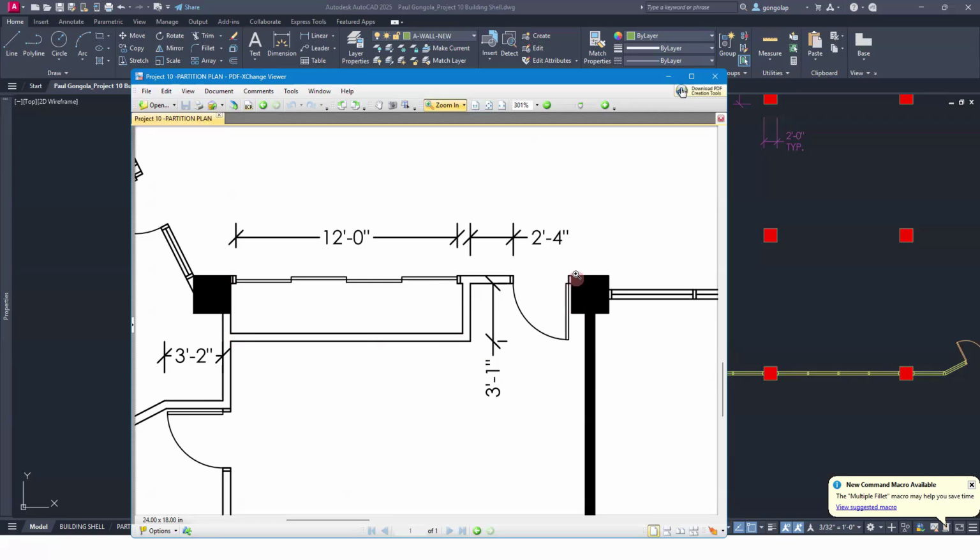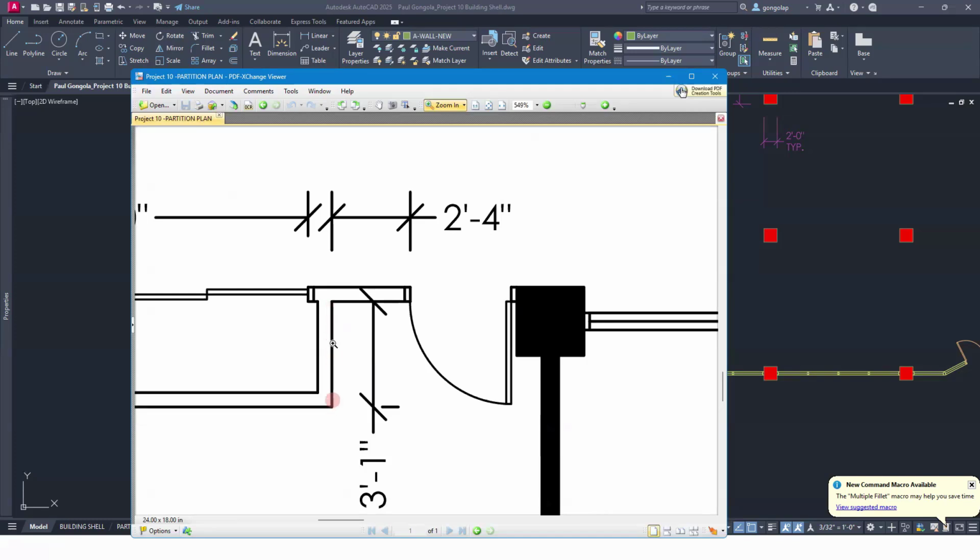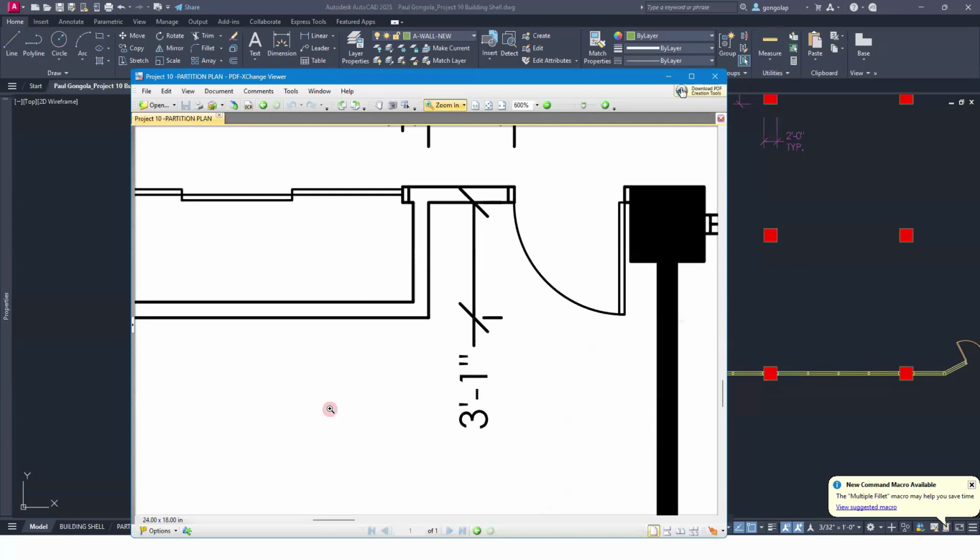And then you want to draw this door. Maybe it'd be better to do it this way. Draw this wall, then draw this door. So offset 2 inches, then offset 3 feet, and then 2 inches for this frame. So then you got this door, and then this partition here starts 2 feet 4 inches from here. So from this inside corner, O-track over 2 feet 4, and then you can come down 3'1".